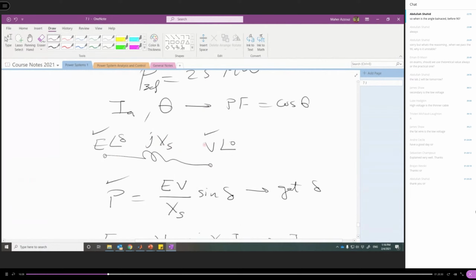It doesn't change because the infinite bus is a source that can absorb or supply infinite power. The word infinite is of course relative, not absolute, maybe 100 times the power generated by the synchronous generator. It is infinite theoretically.